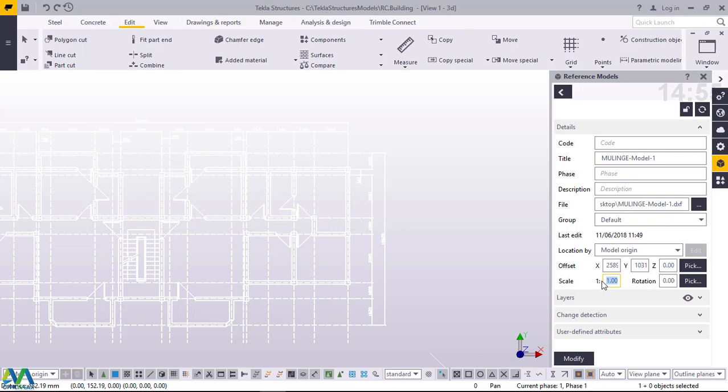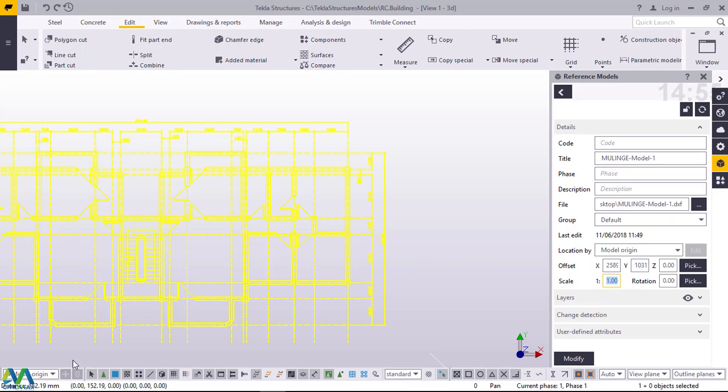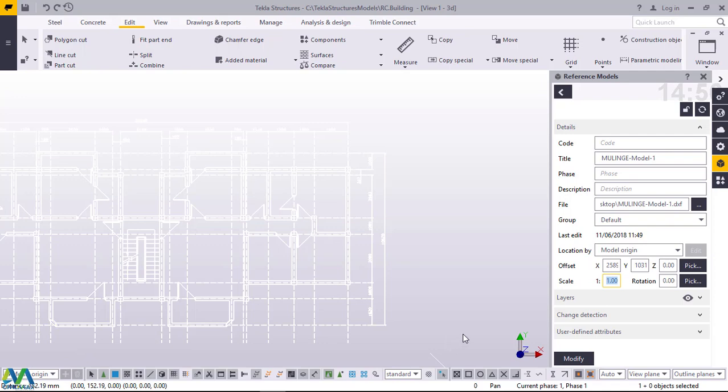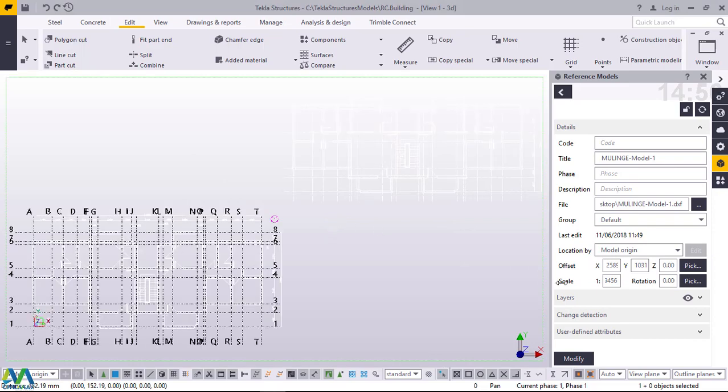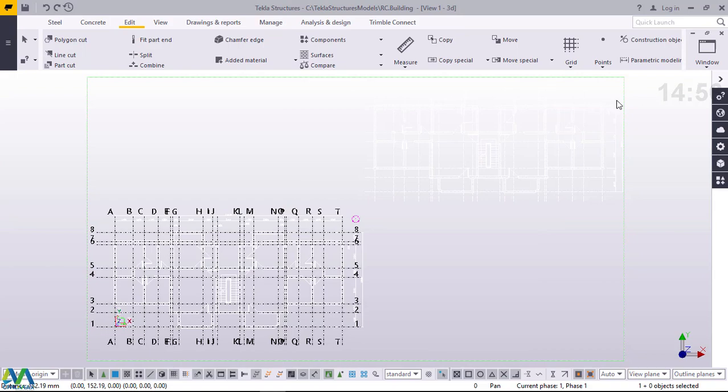Come to scale right there and feed that result that you got from dividing this by the actual measurement from measure here. Then feed that 69.78119456. Then go straight away and click modify. Then click expand. There we are, and we'll go straight away and now close this.